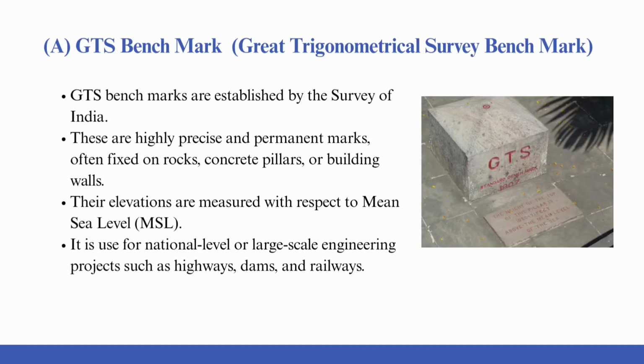The first one is a GTS benchmark, that is Great Trigonometrical Survey benchmark. GTS benchmarks are established by the Survey of India, and these are highly precise and permanent marks often fixed on rocks, concrete pillars or building walls, and their elevations are measured with respect to the mean sea level, often called MSL, and it is used for national level or large scale engineering projects such as highways, dams, and railways.